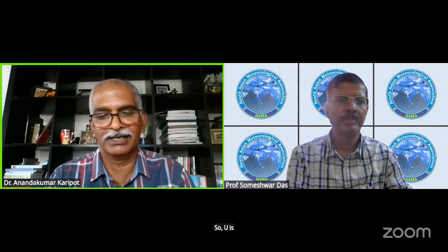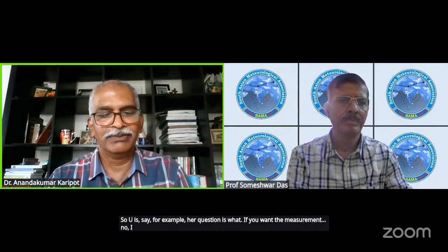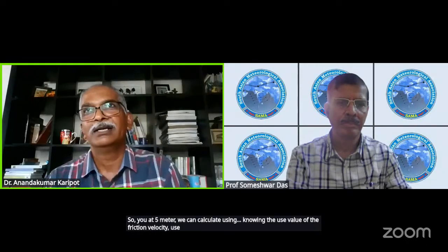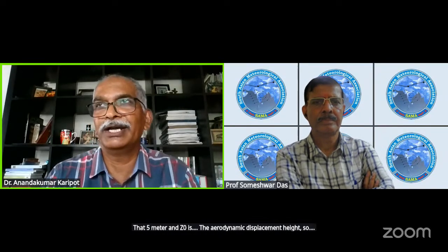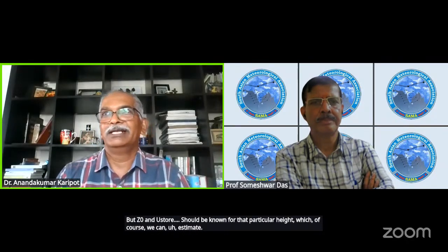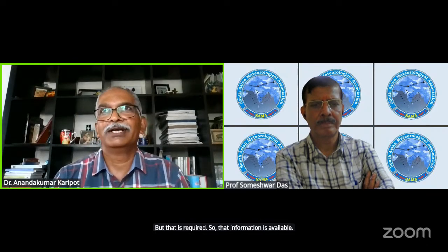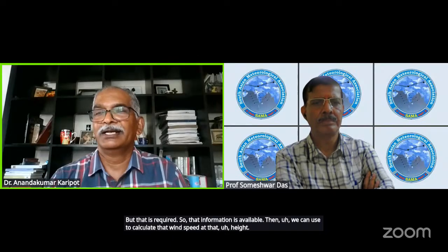Say, for example, you want to estimate the wind at 5 meters. We can calculate u at 5 meters knowing the value of the friction velocity u star, divided by k, which is the von Karman constant 0.4, and multiplied by the logarithm of z by z0. Z is that 5 meters and z0 is the aerodynamic displacement height. But z0 and u star should be known for that particular height, which of course we can estimate, but that is required. If that information is available, then we can calculate the wind speed at that height. And if the stability is not neutral, then stability corrections will have to be applied. So it is possible, but may not be very accurate.